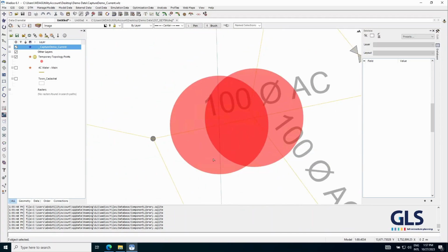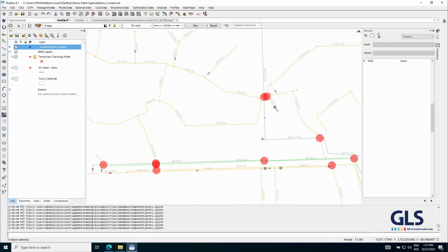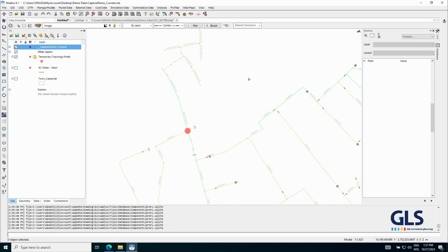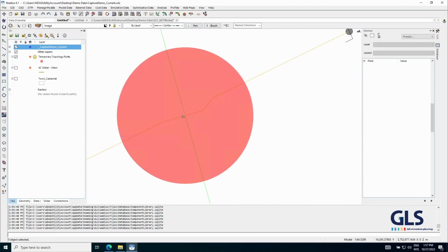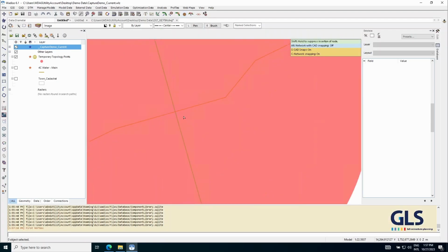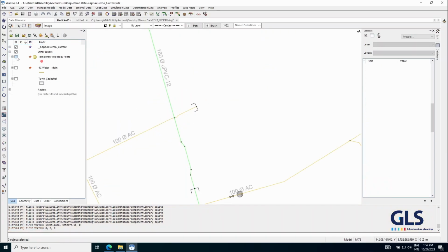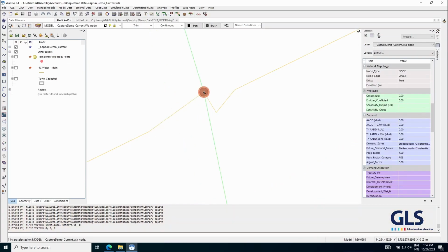So the thing is, not all crossing pipes are incorrect. So that is why we want display. So now we know this is the portion that we've imported. This is incorrect. I actually need to insert a node. Quite simply, we say insert or add a node, and you can go there, get that crosshair, click, it will add a node. If I now just turn this off, if I select this node and I move it, you'll see all of them are in fact connected. So Control Z.